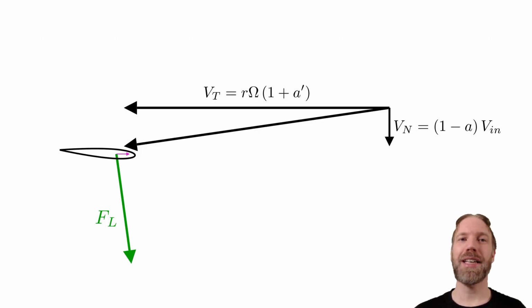Let us take a look at the tip vortices for the airfoil again. If our simplified model with fixed induced velocity is correct, what we would expect is a constant downward velocity due to the tip vortices released behind the blades. What we can see though is that the flow is circulating around the tip vortices with higher flow velocities close to the center of the tip vortex. We have to assume that this distinct tip vortex will cause additional effects that have to be accounted for by our model.